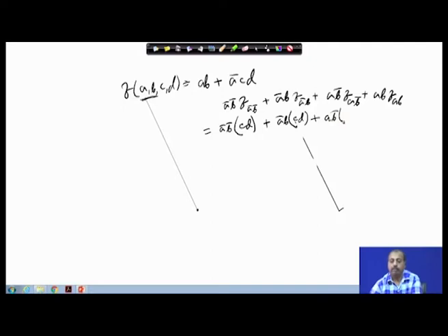into f(a b bar). So, a b bar, the first term again vanishes and in the second term a bar cd, since a equal to 1, this term also vanishes. So, this is 0 plus a b into, this is a b, if this term evaluates to 1. So, this is 1. So, my final function becomes a bar b bar.